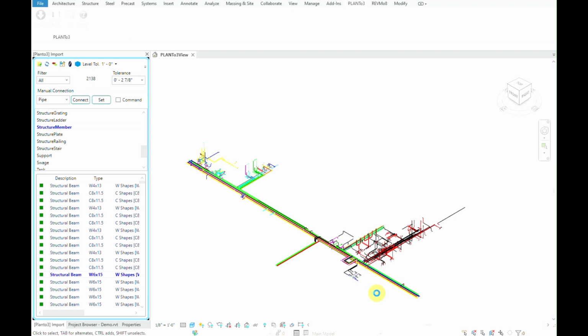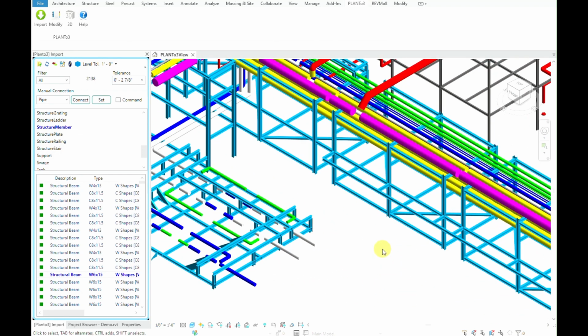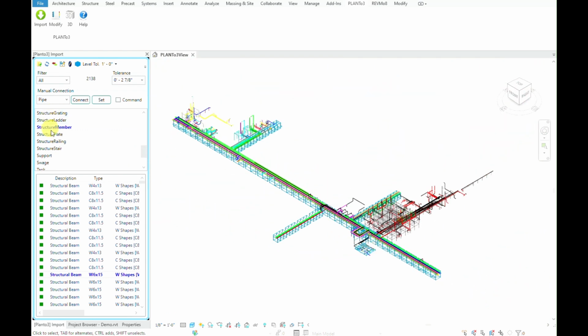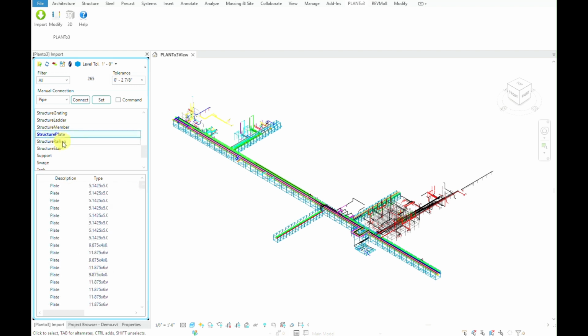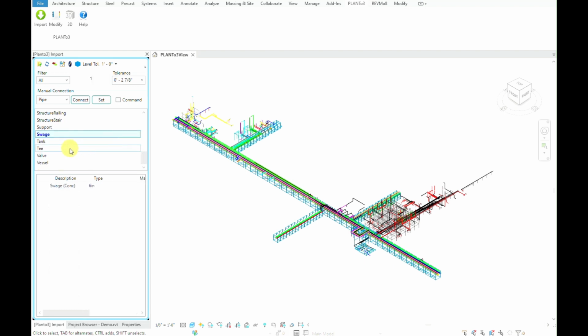Create Geometry options as opposed to Create Instance will create the exact geometric shape, but as a generic model and not a family type-based element. You can continue to create the rest of the imported entities using the same steps.